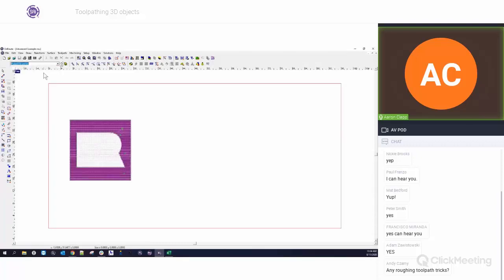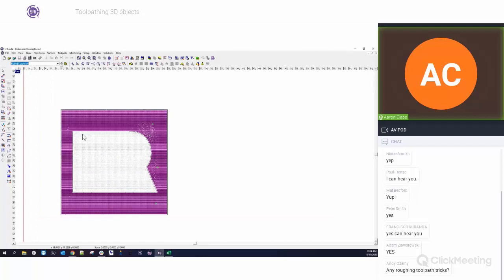Then on the raised flat portion, here's what I'm doing. I'm actually using a contour to create a raised flat portion on my job. And what I've done here is I used the masking that we just showed. I just created an outline on the letter E and the letter R so that it created this nice little shape, because I wanted some letters to stand out on top of a flat platform. And you'll see what I mean in a second. So I took a mask, I toolpathed it, and so now I've got this nice platform to cut on.